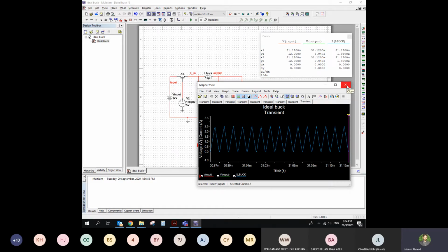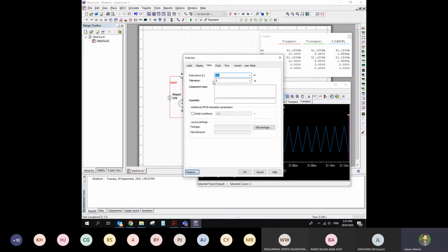So that's why, to understand the behavior, minimizing the inductor ripple is not always the goal. Sometimes inductor ripple is important if we want to operate in discontinuous current mode. Inductor ripple, we have to accept it, and we have to induce it by using a different value of the inductor. So it's not about minimizing or maximizing, it's about what we are looking for. If we want to compromise the efficiency but maintain the output exactly at the theoretical value, we can do that. Or the other way around, we can come up with a lower ripple.